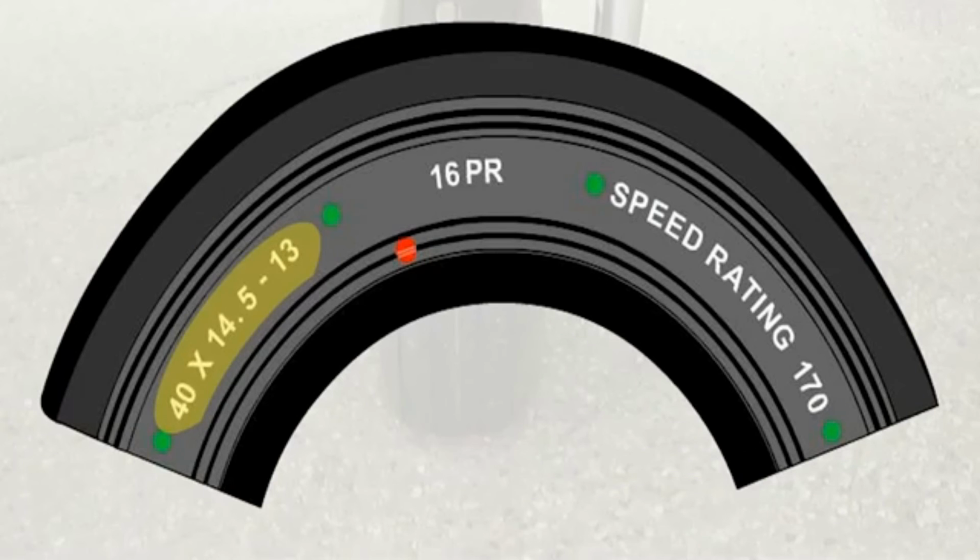The size of a tyre is marked on its sidewall and includes the outside diameter, the inside diameter and width of the tyre, all in inches. The ply rating, the index of the tyre's strength, is also marked on the sidewall. Normally it's shown as an abbreviation, for instance 16PR, but occasionally it's shown in full as 16 ply rating. The speed rating of the tyre, the maximum speed for which it's designed, is imprinted on a panel on the sidewall of some high-speed tyres.